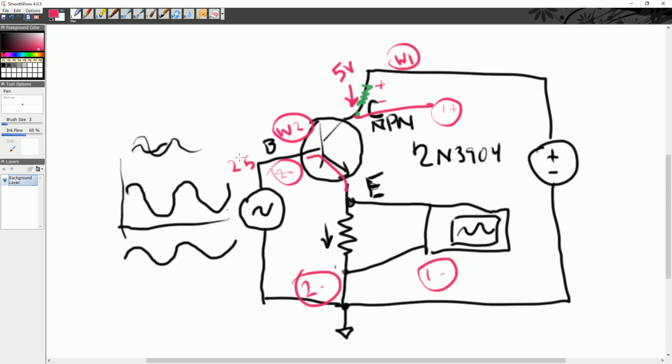Normally what you do is you would be biasing, so usually over here, let me change to a different color. Usually over here, you'd have a signal source. In a normal scenario, you'd have a single signal source, you would capacitively couple it in, you'd have the rail, and then you'd have bias resistors here, right? This is what normally happens for a simple Class A amplifier. But in our case, we're replicating this entire blue section with